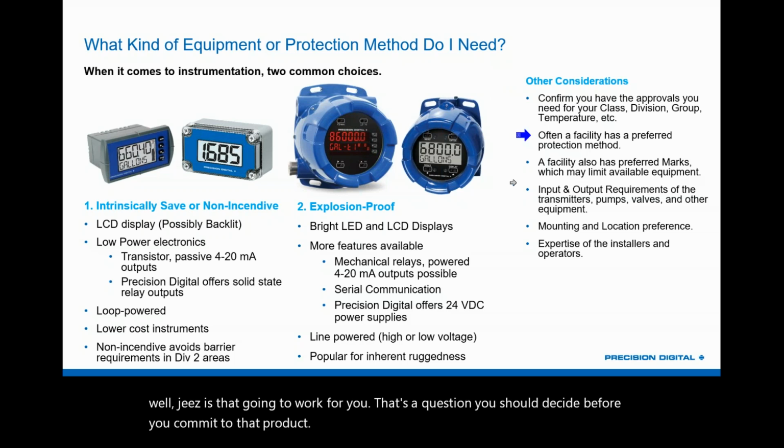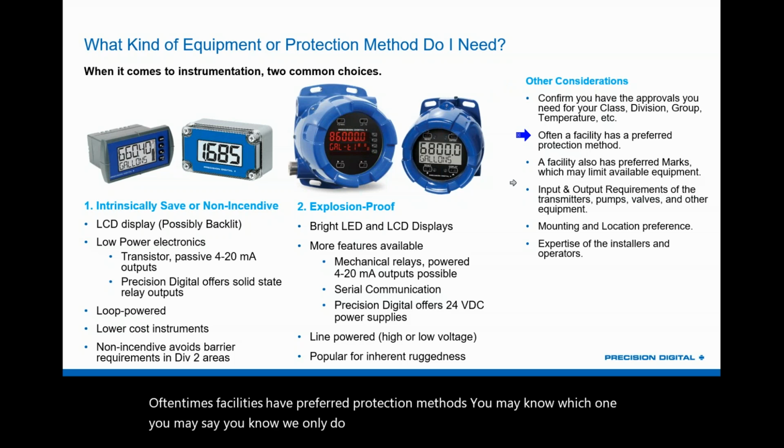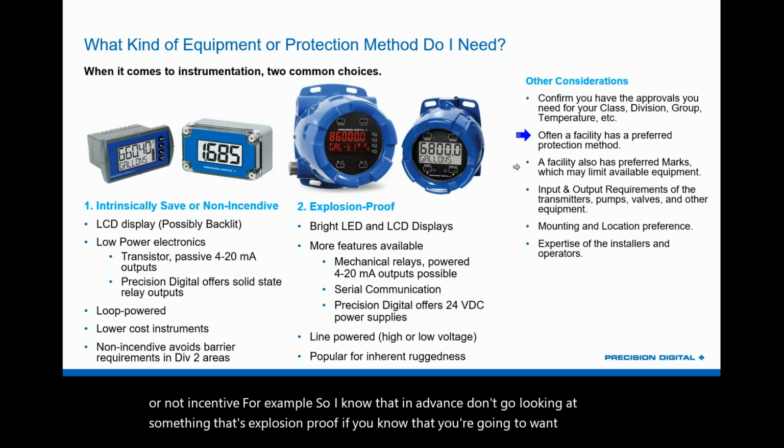Oftentimes, facilities have preferred protection methods. You may know which one you like. You may say, you know, we only do explosion proof, or we only do intrinsically safe, or non-incendive, for example. So know that in advance. Don't go looking at something that's explosion proof if you know that you're going to want to install an IS device instead.